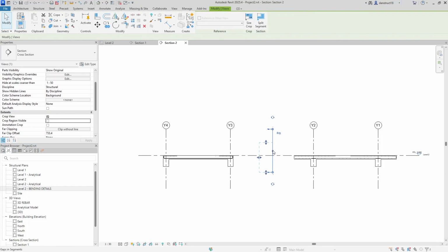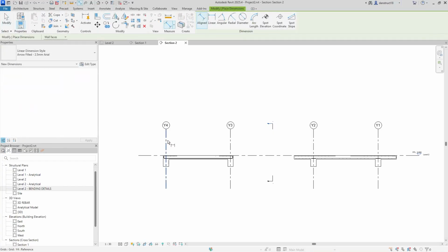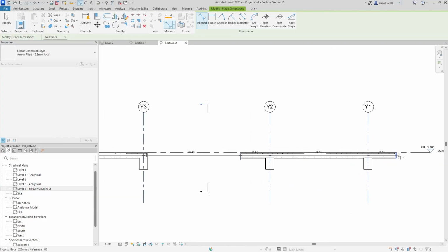And now I'm going to add a gap in the section 1 annotation. I'm just going to add a gap like this. I'm just going to drag it up. I want to make sure I'm utilizing space as well as possible. So I'm going to add the dimension between the spans, and I also want to consider the slab overhangs as well here in this case, and in the other end as well for the cantilever. Just going to make sure I reference it properly.